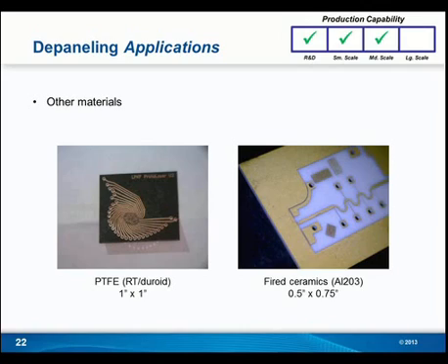And it is common for other lasers on the market to drill ceramics very fast. And the UV lasers, because of the wavelength and absorption with Al2O3 and ceramics, it's a slower process, but it's cleaner. Yes. So you can drill faster with CO2 type lasers than you can with UV, but you do have higher energy, higher heat, higher slag. So the UV is a little slower, but a cleaner process.